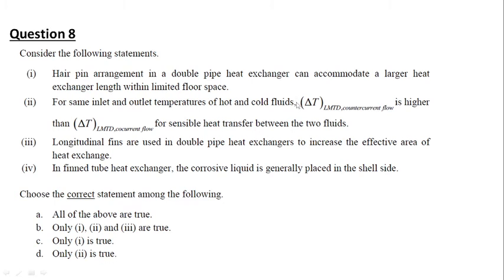So when there is a phase change, then the LMTD of both counter current and co-current will be the same. But in sensible heat transfer, the LMTD of counter current will be greater than co-current.